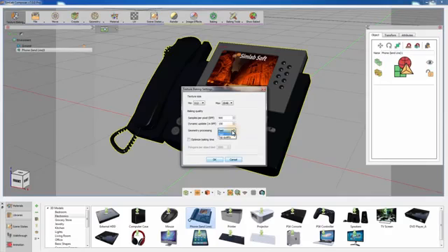The Geometry Processing is an advanced calculations tool that resolves any stretching issue with the texture. In most cases, the Fast option would not cause any stretching, but in very rare cases the complexity of the model's design might demand the use of top quality to eliminate any distortion in the baked texture. Optimize Baking Time can divide a single object to multiple objects, each with a unique texture map assigned to it, according to the number of polygons it has. This option is mostly used to create high-quality texture maps to proportionally large objects without the need to increase the resolution of the maps dramatically.